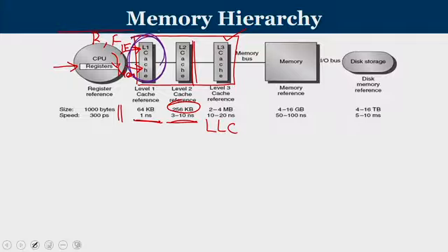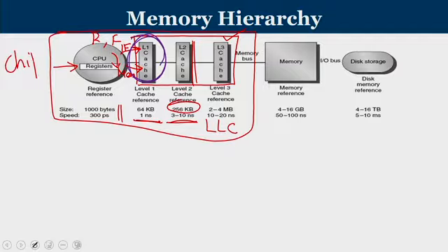So the whole thing is inside your processor chip. This is your chip. Now off chip, the first level of off chip memory is your main memory. It is also known as DRAM nowadays, because of the technology being used, dynamic random access memory. And then we have the hard disk, that is for permanent storage. Once you come to off chip, your memory capacity is in the order of gigabytes and terabytes, and the access speed goes into the milliseconds range.